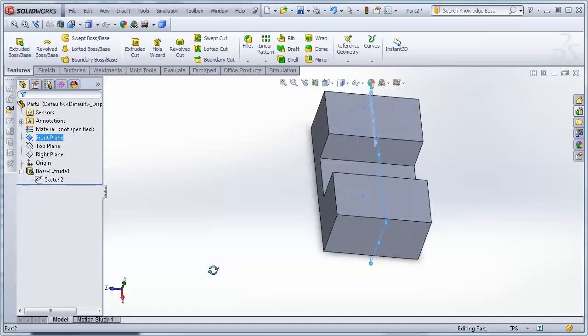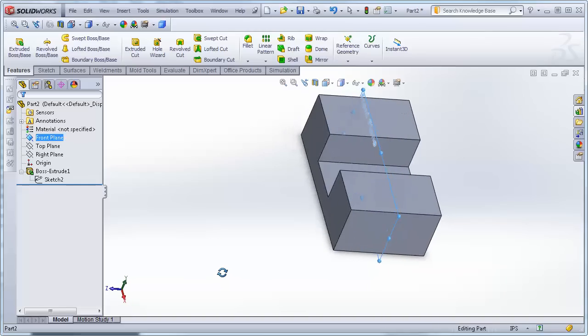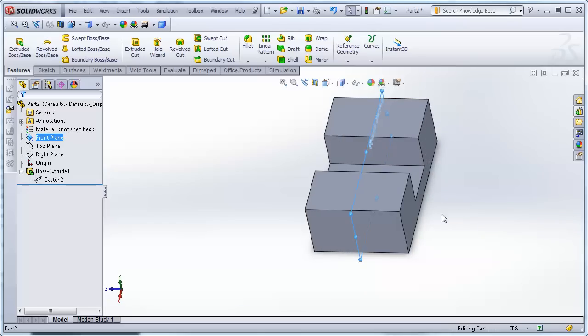My sketch plane still lies in the middle of the part, and maybe I can implement some mirroring and symmetry for various things that I might do to this part, because I have this sketch plane in the middle of the part and not at one end. That would be another very important decision that captures my intent for when I start changing this part later. Because I might wish to dimension things not from an edge of the part, I might wish to dimension them from the center of this part, etc.